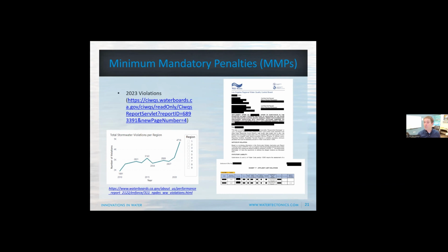I haven't really seen that happen yet, but I know it's been brought up, and the longer it goes on, I think that's a risk. The other risk is if you're in the crosshairs of a third-party group or other citizen suit. An effluent violation is a very clear permit violation: the state says so, therefore we know you're bad. Versus an effluent exceedance on an NAL or a TNAL, where you can say we're aiming for it. Exceeding an NAL or a TNAL is not a permit violation. So there's also that risk of exceeding on the NALs.